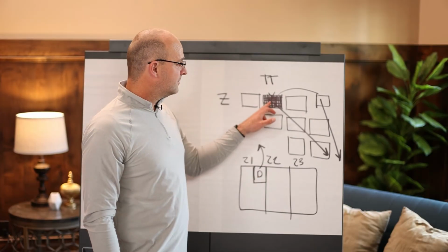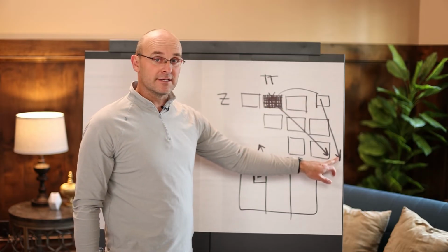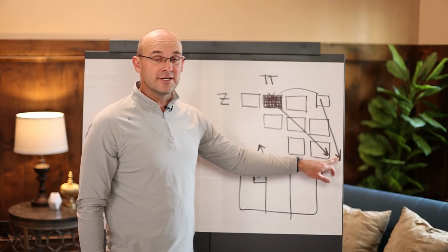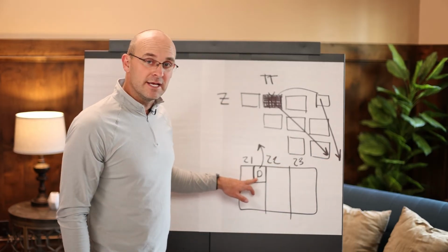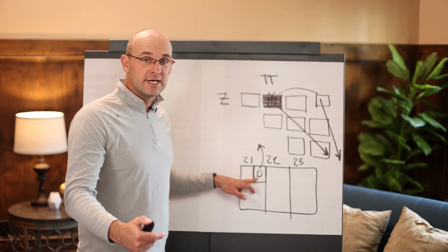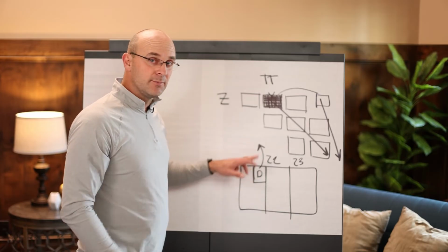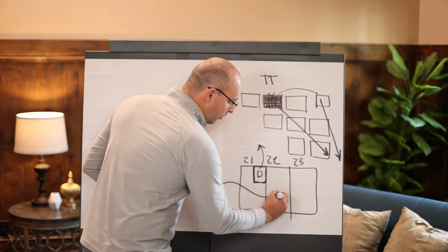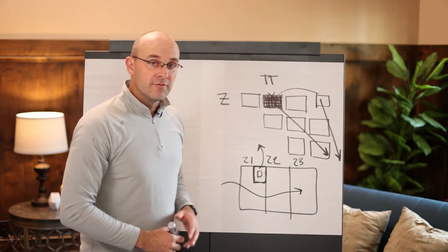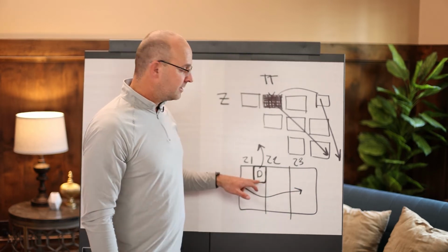And so if you ever have to do this and manage it on its own tact time, show that visibly in the schedule or on a pull plan or on a scrum board. And if you ever have to pull out work from the actual zone itself, then make sure that you pull that out, show the trades that it has been delayed, work your normal flow of work around it, and again, pull that out.